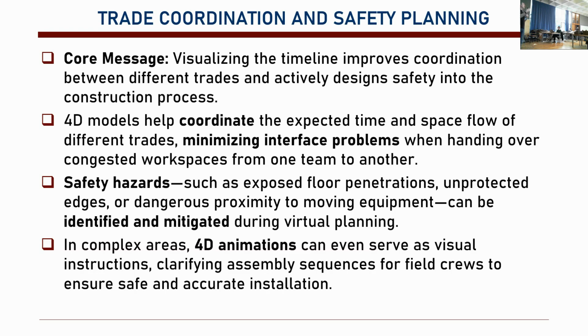So how do we make sure that different construction people work together in a fluent manner? We minimize interface problems in that case because we have congested workspaces. We have something called workspace definition too. Remember, I mentioned the soft clash for this box, but that clearance clash was for operation. For construction, we can create other workspaces too.